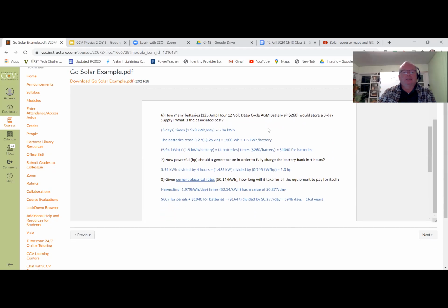So there's another prompt that says, okay, well, if you're going to store that, and the sun doesn't shine every day, we should probably have like a 3-day supply, especially in the rainy season. And even in the rainy season, we might have to get a generator to charge the batteries instead of the solar panel. So if we're going to harvest enough to store a 3-day supply, then we really need to harvest about 6 kilowatt hours a day, or we need to be able to store 3 days worth.